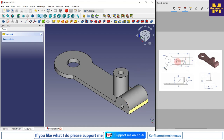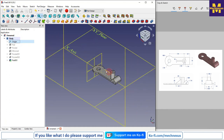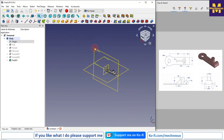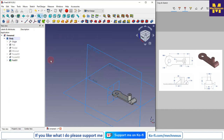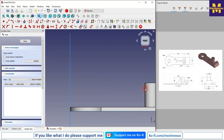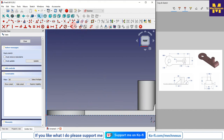And now we will add one triangular plate. So for this I will on my origin plane, as I have made my part symmetric, so I can simply select this plane and I will say sketch, and now here I will project this outer edge of my circular boss and the bottom edge.